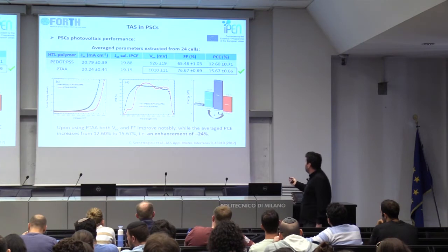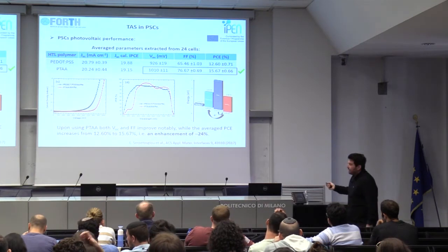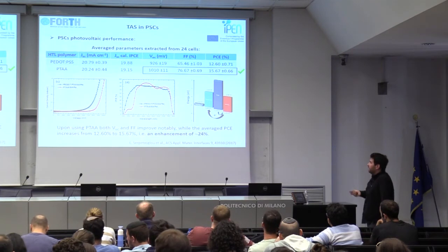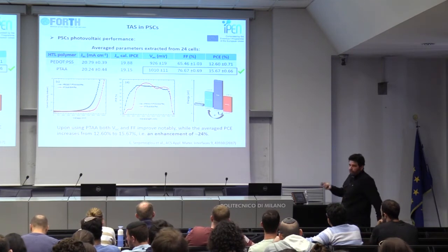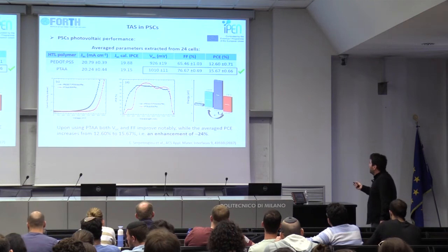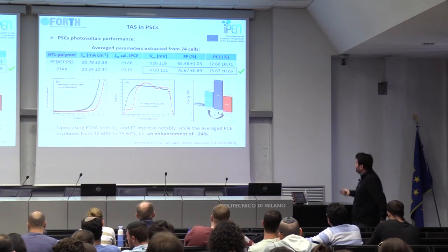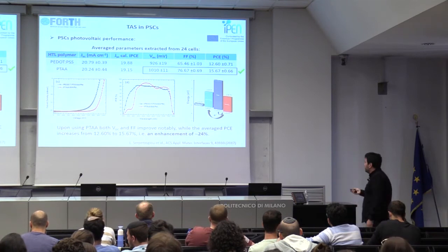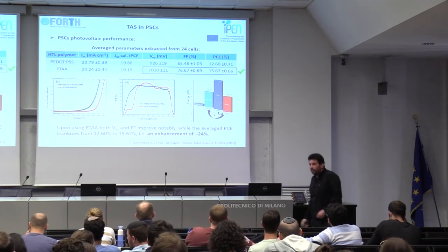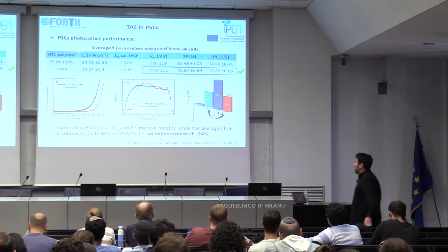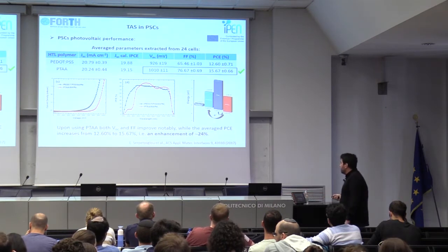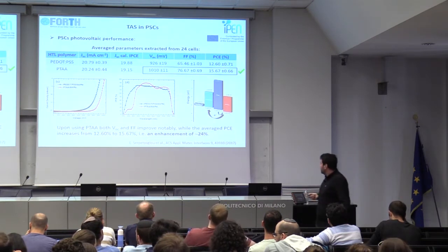And it becomes immediately obvious, and remember this is the average, not the champion devices only, that by simply introducing the PTAA polymer as a hole transport layer, you raise the power conversion efficiency from 12.6 to almost 15.6, which is an enhancement of 24%. And this is mostly attributed to the increase in the VOC, the open circuit voltage.